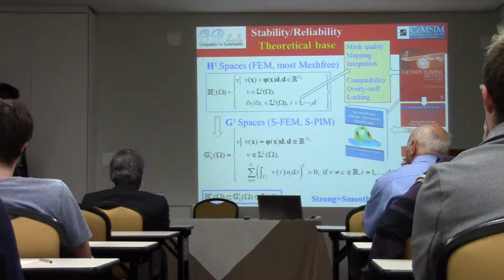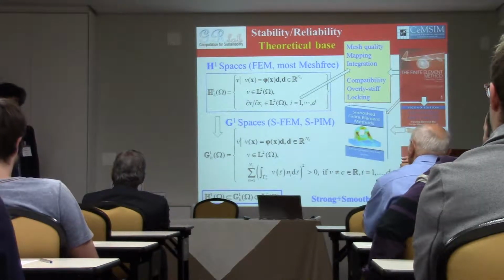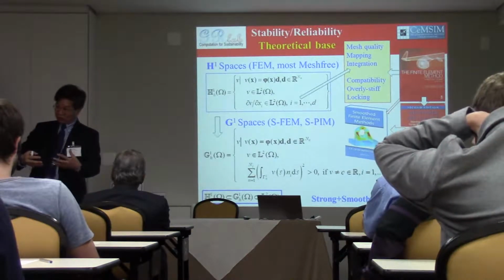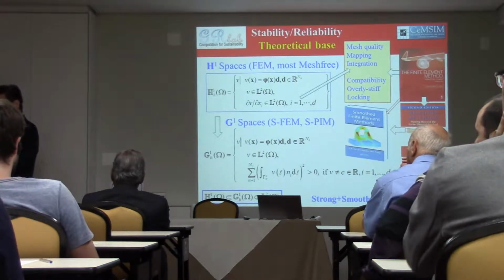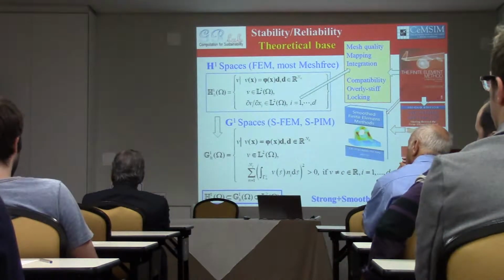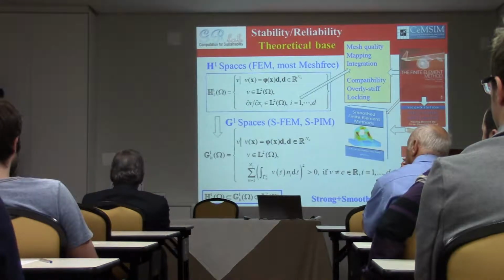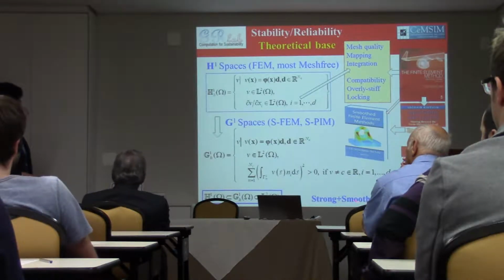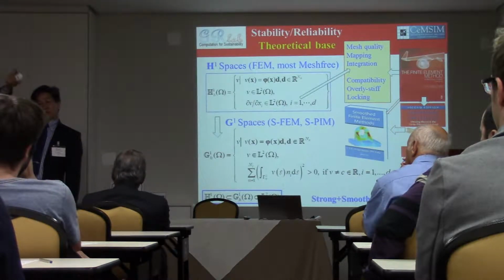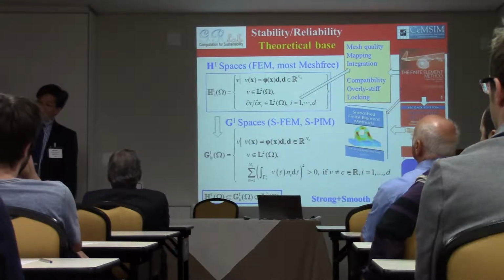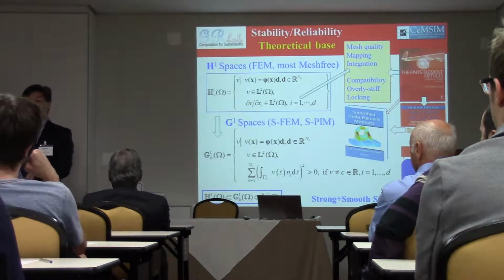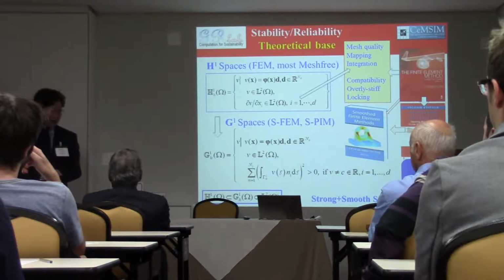In the SPH, it uses the so-called smoothing operation. In the smoothing operation, basically it's a technique for us to approximate the function and the derivatives of the function. And in that process, I try to use smooth functions that always have a bell shape. Okay. Now, that approximated function is packed into the strong form formulation. So if I choose a proper smoothing function, and I perform an approximation always locally, then I can make sure the system equation I create is going to be diagonal dominated.